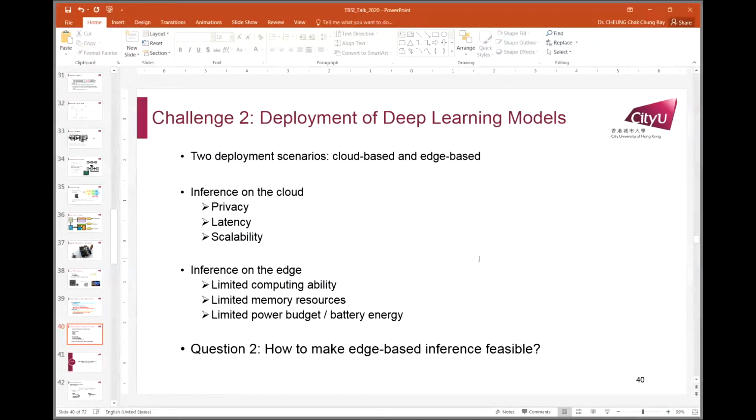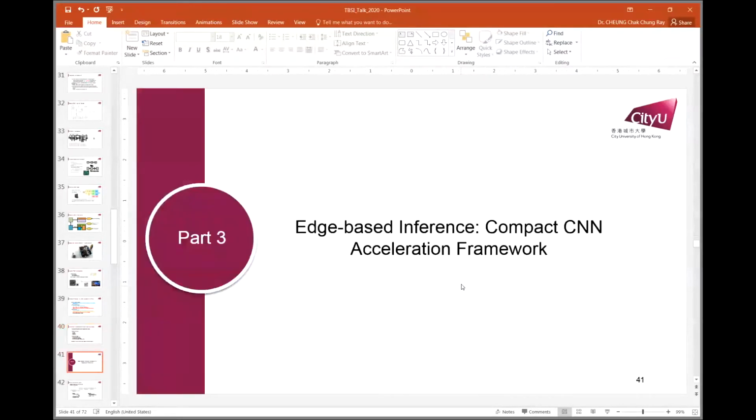So our scenario is that we want to have a system in which all the tiny nodes are empowered with a RISC-V, and again, they're very smart. They're intelligent. So how can you make the edge devices able to infer by themselves? We are able to propose what we call a compact CNN model. We want to do a binary CNN. So the tiny data put into the chip has been really compressed, including the bit width and the model, the number of parameters. We want to optimize these 2 parameters.